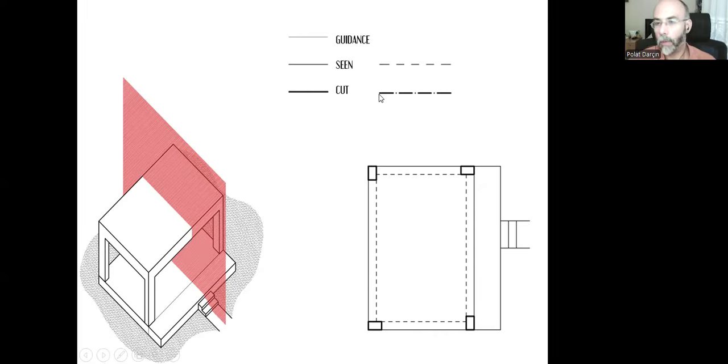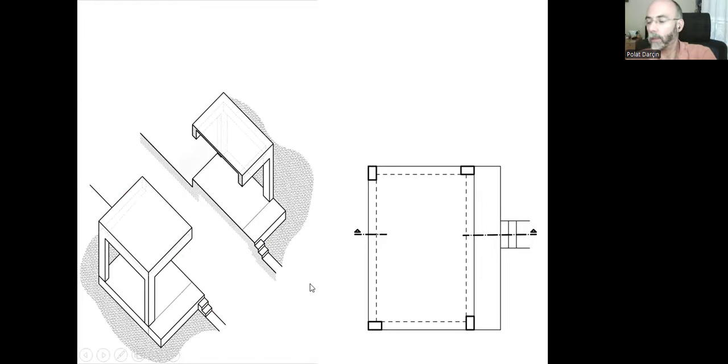Here, this time, we are going to do a straight line, a small gap, a point, another gap, another straight line. And these straight lines need to be equal to each other and gaps as well. And it goes like that. So we can create that thick line in this shape to indicate that we are providing the section in this direction. That means that we are separating this, dividing the whole structure into two pieces. Now we are in the middle part and we are looking towards that direction.